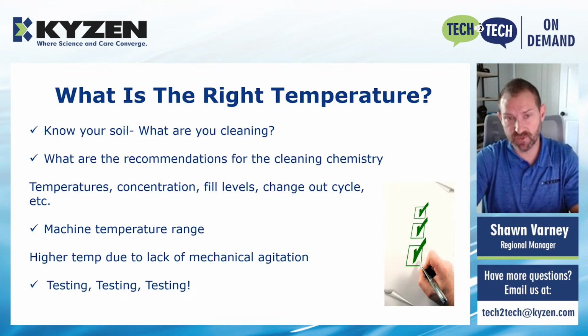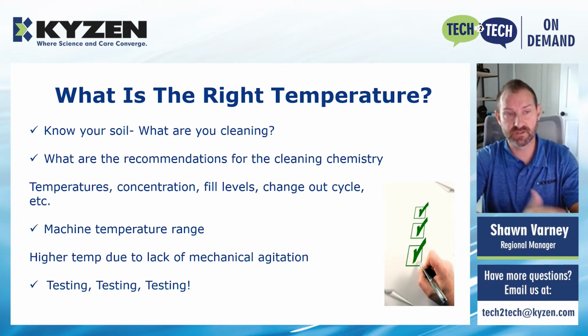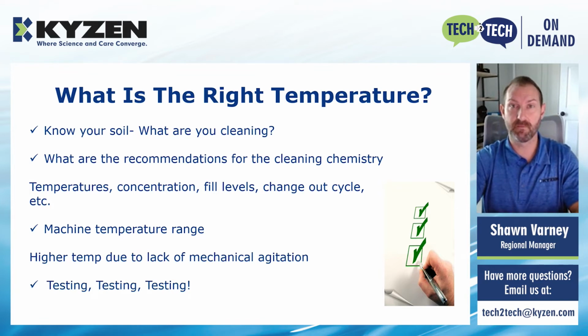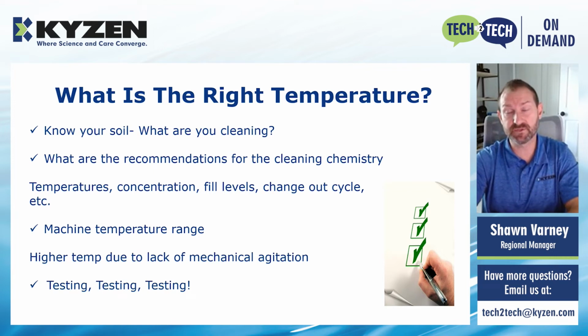There are a lot of things to consider when you're going through that, not only what we just discussed, but also just knowing your soil. What are you cleaning off? Are you cleaning off just some debris, some dirt, or oils, or are you cleaning off baked-on carbon that will require the higher temperature to really separate it from the engine block and clean it properly? What are the recommendations for the cleaning chemistries? Know that your temperatures, your concentrations, your fill levels, your change-out cycle, all the stuff like that is going to affect your temperatures and how long you can keep that bath life.